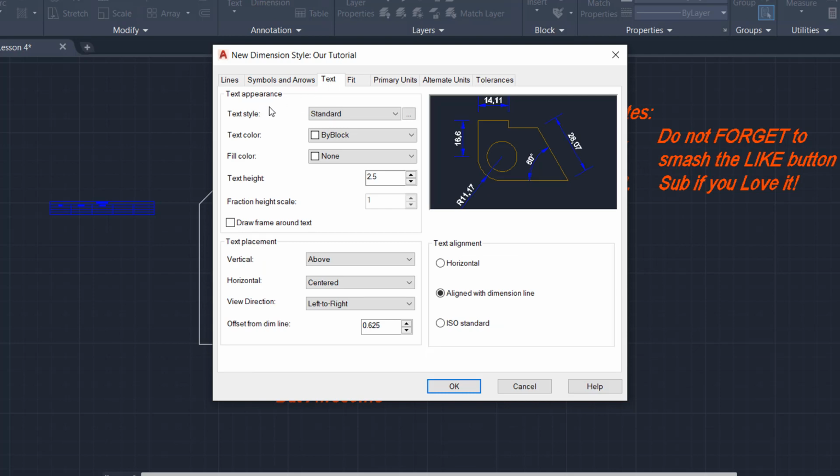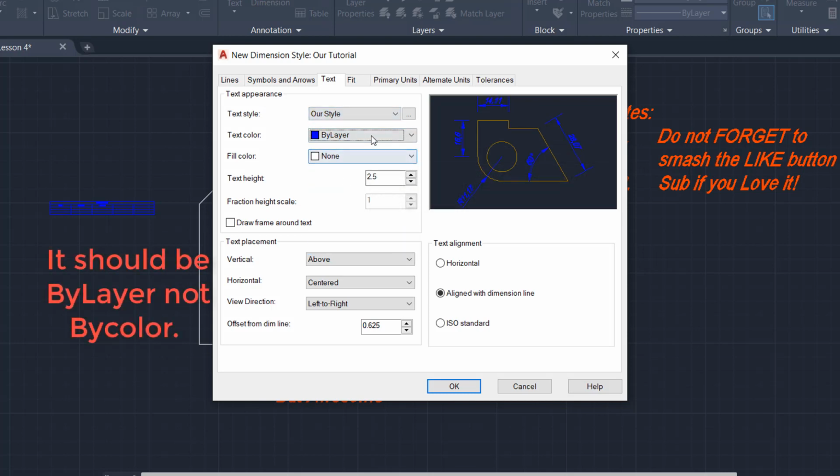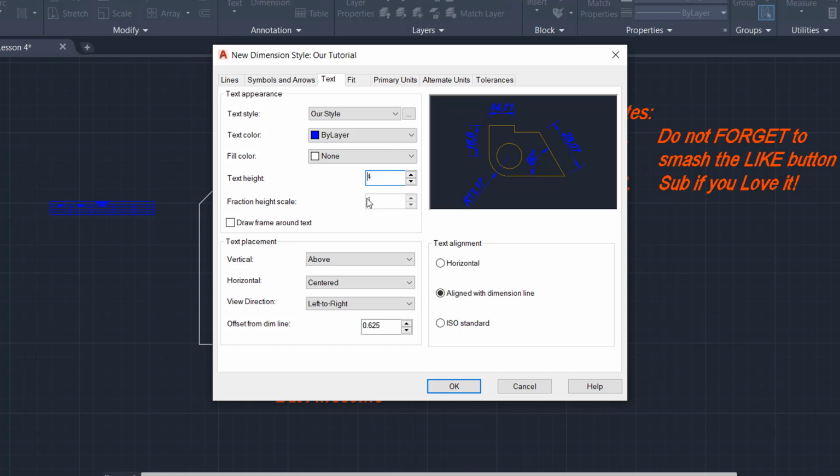Text style, choose from a text styles you have already made. Text color, I will make it bicolor. Fill color, I advise not using it because it will make an untidy look. Text height, let's make it 4. Text placement, for vertically it's above the dimension line, for horizontally it's centered. You can work through them and make your own preferences. I do like it this way. View direction, if I change it right to left, can you see that it changed upside down? That's pretty handy sometimes. Change it back, we don't need that right now.